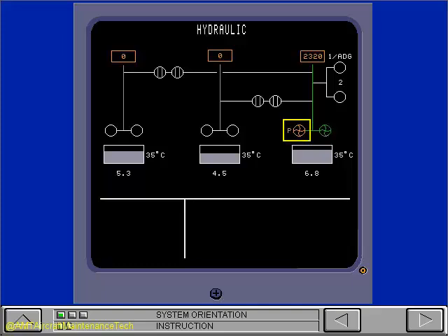If an engine pump failure occurs because the pressure decreases to less than 2400 psi, again the left pump will show an amber circle with amber veins. An amber P will show adjacent to that pump on the synoptic. If the case drain temperature for an engine pump increases to more than 118 degrees Celsius, an amber T will show above that pump on the synoptic.